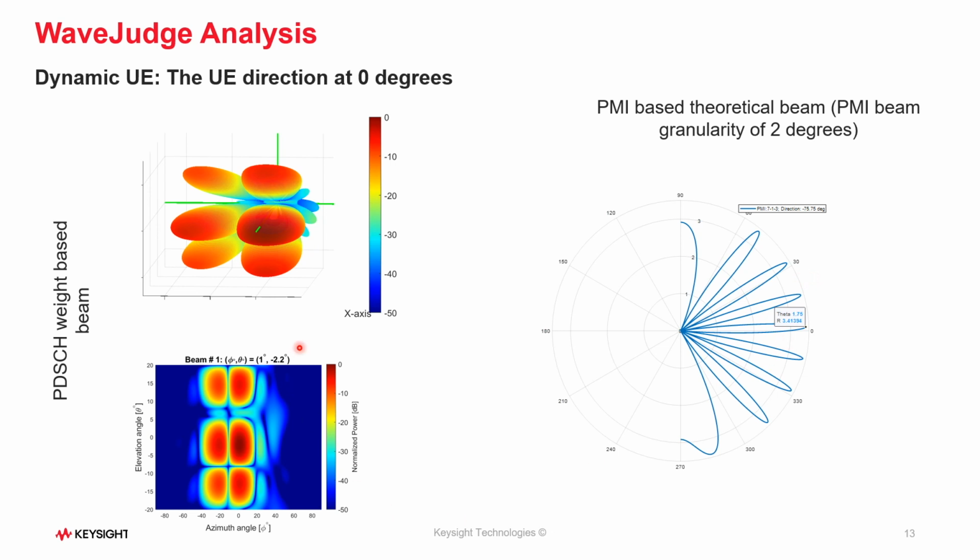And we can also observe a very interesting fact here. The side lobes in the elevation plane are a bit stronger. This is because one RF port actually consists of multiple stacked antenna elements, and this antenna element pattern eliminates the strong side lobes in the elevation plane. So in reality we don't have these strong elevation plane side lobes.